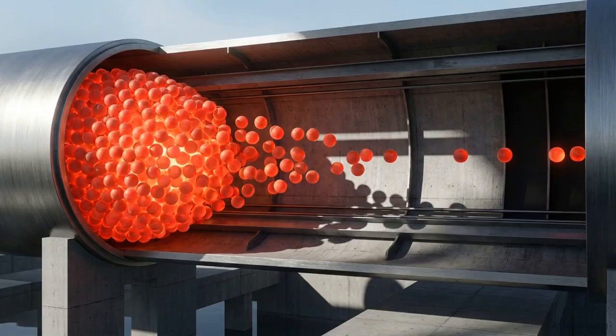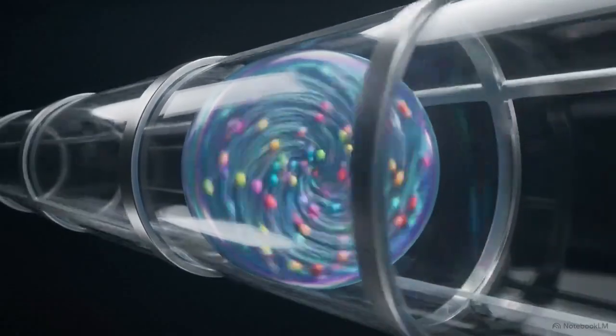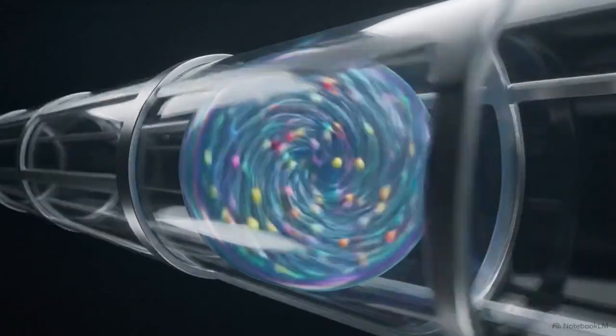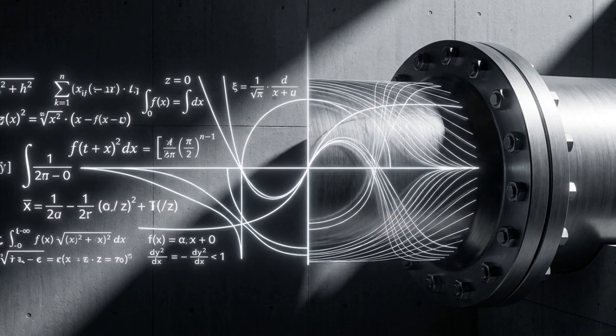As the isolated plug advances down the spatial axis, the initial inlet concentration systematically drops as the raw reactants are consumed by the process. While the flow strictly prevents any mixing backward or forward, the molecules within each individual plug are constantly mixing radially. This internal churn guarantees a uniform chemical conversion from the center of the pipe all the way out to the physical walls. Maximizing conversion efficiency requires taking this abstract calculus and building it into a rigidly controlled physical architecture.